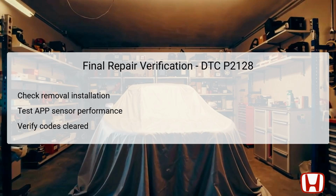After completing the necessary repairs associated with DTC P2128, a final verification is crucial to ensure that the issues have been resolved. Recheck all removal and installation processes to guarantee no additional components were inadvertently affected during service. Next, test the performance of the new or repaired APP sensor to confirm that it is providing accurate voltage readings as expected. After that, clear any DTCs from the PCM and examine whether the issue reoccurs by monitoring the vehicle's performance during a drive cycle.